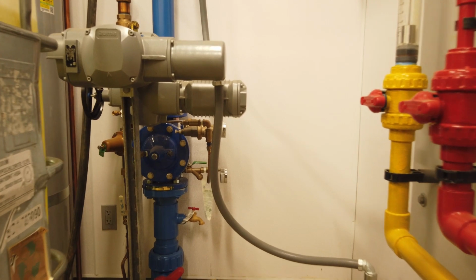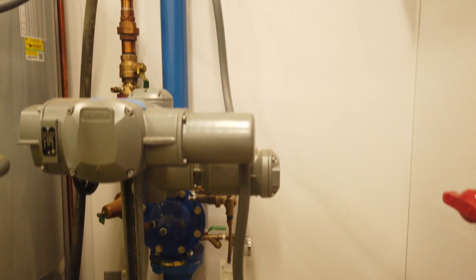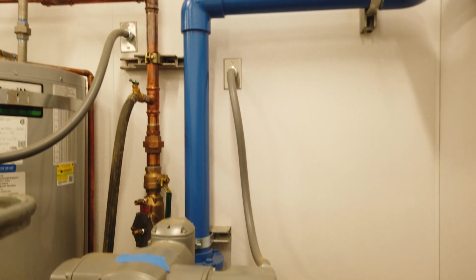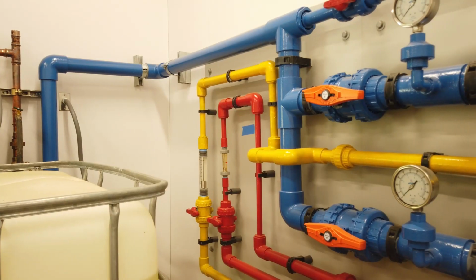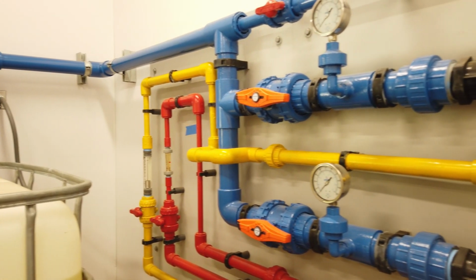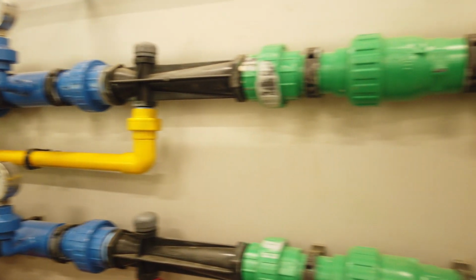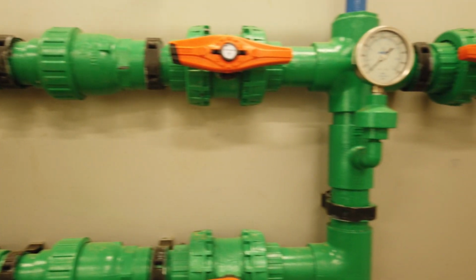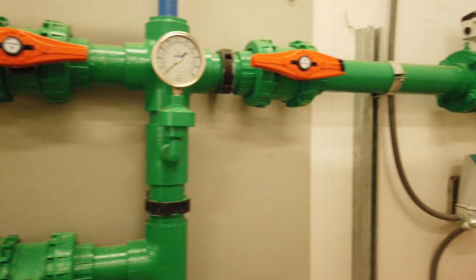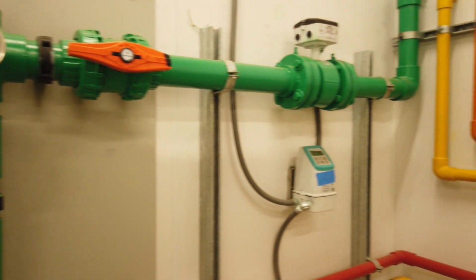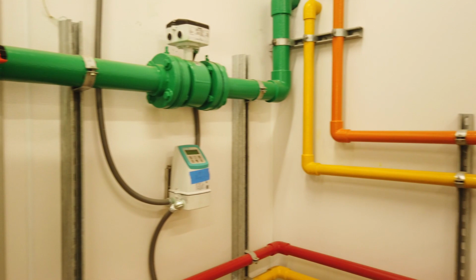The chemical room also includes a chemical clean-in-place skid for the MBR system. Typically, once or twice per year, the membranes are cleaned in place with a very low concentration dose of sodium hypochlorite. The low-dose sodium hypochlorite is injected with a Venturi injection system. The total volume delivered is managed with a magmeter.